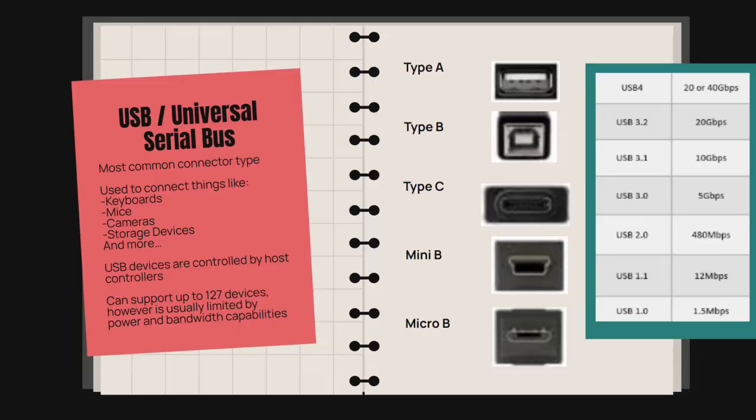Now when you're working with USB, cable length matters. Low-speed devices can handle up to 3 meters. Full and high speed can handle up to 5 meters. Super speed, shorter recommended lengths are necessary. USB can also provide power. Standard ports supply a few watts, while USB Power Delivery can supply up to 100 watts of power, enough to power most laptops and monitors.